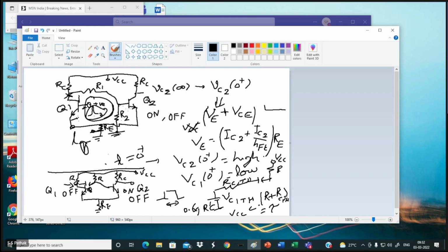My goodness. I'm looking at the wrong diagram. Here, sorry, I have given an open circuit here. So VCC through RC is coming at this point. That is my VCC, because for Thevenin's equivalent I have to see how much supply is coming over there. So how much is my Thevenin's equivalent resistance? I have given a cut here. Voltage source is grounded, so it becomes your RC.